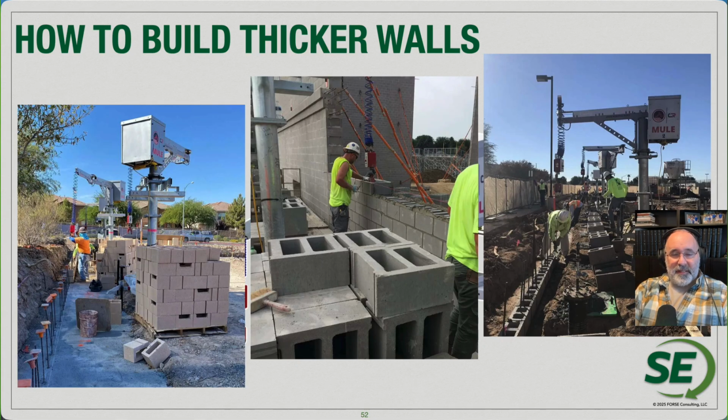It also does kind of make me pause a little bit. There have been people through the years, as I've been working with the different coalitions for masonry, that different design firms that we've went into that actually didn't know that they still made 16-inch masonry blocks. So they still make them. They're still readily available, and we can certainly utilize those in below-grade construction, where, again, utilizing some of these thicker elements can make the compatibility with the wall systems above work out.